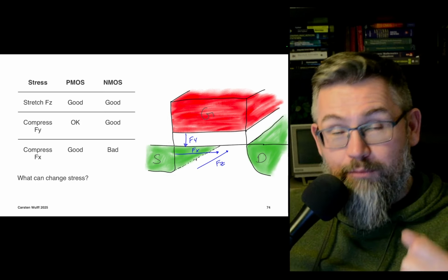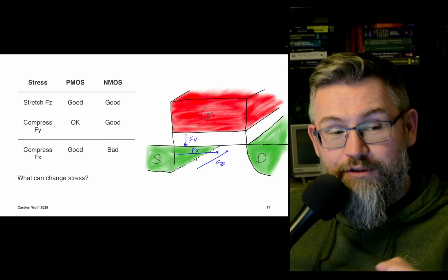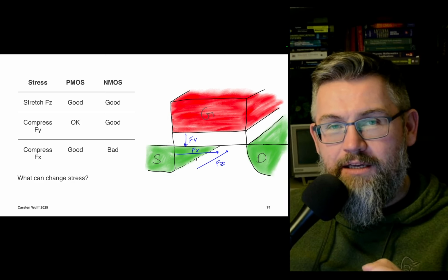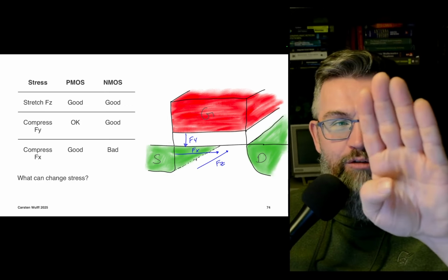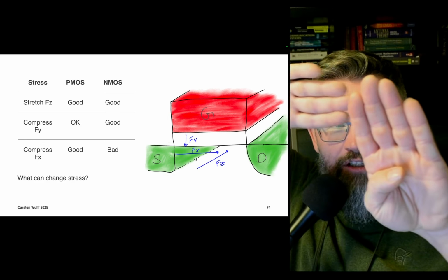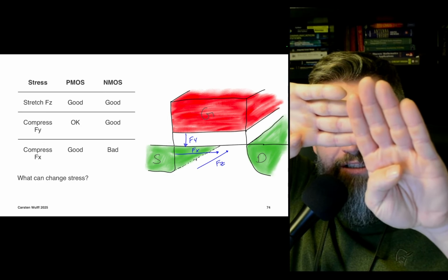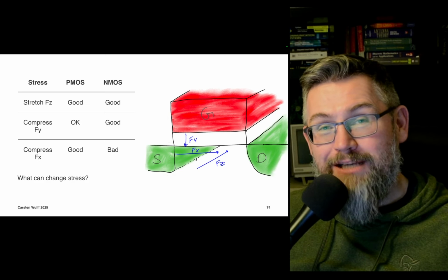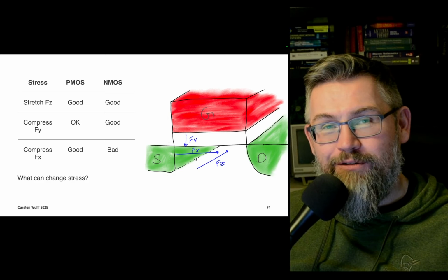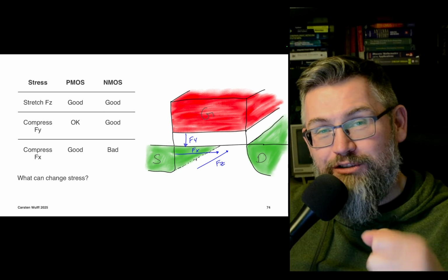And we're really talking about strain here. So physically pushing on the PCB, if you do your layout wrong, like you have your current mirror with one transistor in this direction, and then you rotate the other transistor, and you do it for PMOS, then you can probably measure that current mirror current changing as you apply stress to the PCB.